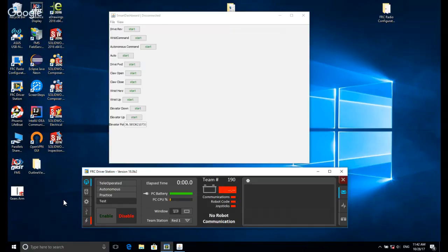If you have multiple plugged in, straight out of the box, you can change them one at a time. It'll figure out to only send this new ID to one of the 10 zero Talons. So what I do is I'll say, oh, assign that one to be number 30. And then I'll go through, get rid of all the zero Talons, and then go back through again and reassign all the numbers that I just assigned to the ones that I actually want. So I'll say, you're going to be Talon 1, you're going to be Talon 2, you're going to be Talon 3, you're going to be Talon 4. It flashes the lights on the Talon that it's selected so you can see which one you're programming. So you know whether it's the left front or the right rear, that kind of stuff.